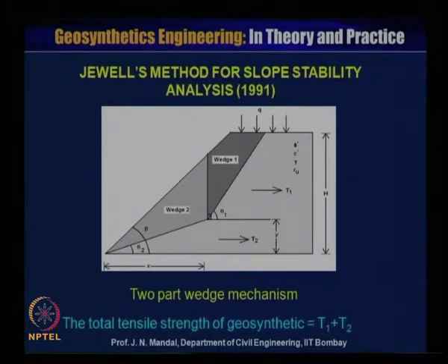There is reinforcement at the top and also at the bottom of the reinforced soil slope, and the length of the geogrid material is variable. In addition, the potential failure surface is curved, that is, a logarithmic spiral, and this design chart is good and also more accurate.